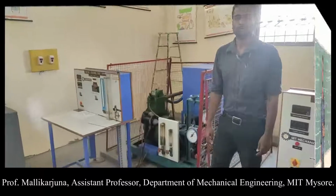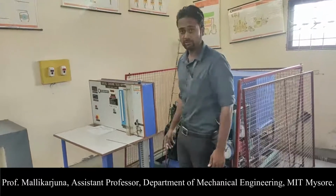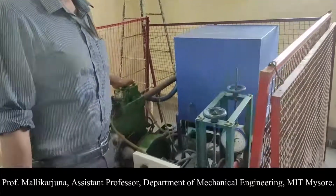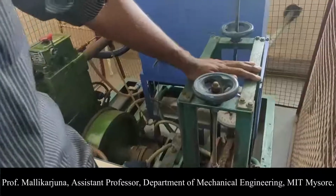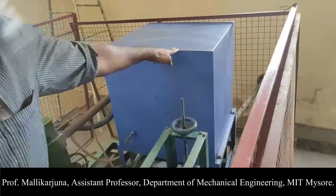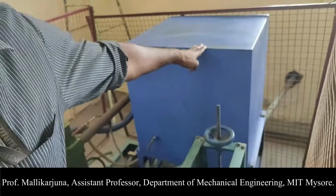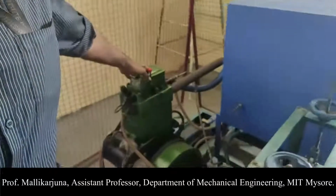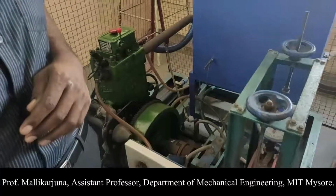So now we can directly move on to the experimental setup and then conduct the experiment. Okay, here we are with the experimental test rig of a four-stroke diesel engine. Let us look at the various components of the test rig. This is the engine portion whose performance needs to be analyzed. The engine has to be loaded with this loading device, which is nothing but the brake drum dynamometer. In order to supply the air, this is the chamber through which air is supplied. This chamber is going to stabilize the airflow into the engine. So these are the few main components required in order to look into the performance of the engine.